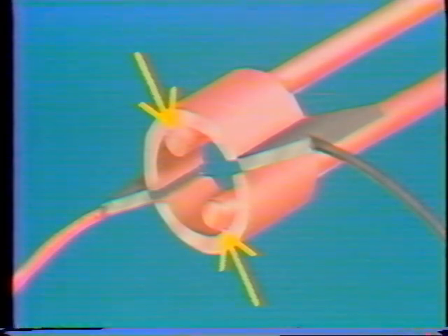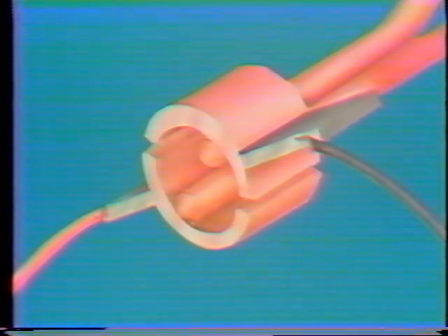This is how a basic DC motor is built. This permanent magnet provides one of the magnetic fields. The magnetic flux lines leave the north pole of the magnet, cross the gap, and enter the south pole. In the middle of this field is the current-carrying conductor, a loop of wire. Each end of the loop is connected to 1 segment of a commutator, which rotates with the loop. The commutator segments slide against the brushes, which supply DC power to the loop. The loop is both the rotor and the armature in this motor. Remember, the rotor is the part that turns, and the armature is the part that carries most of the current.